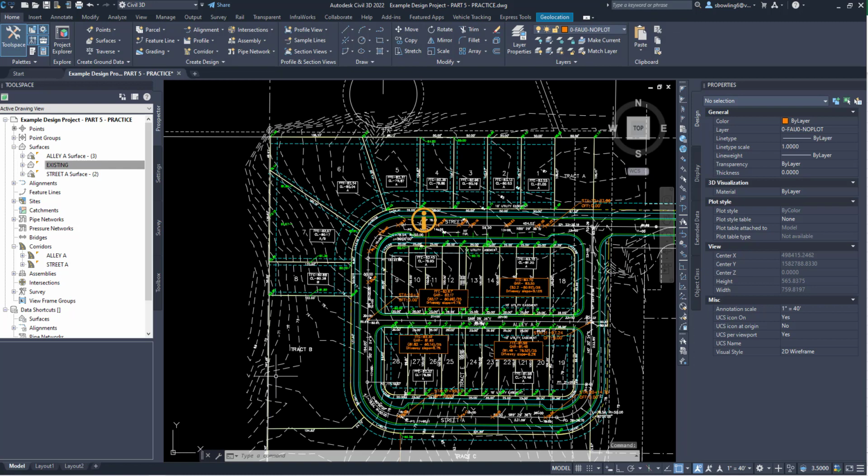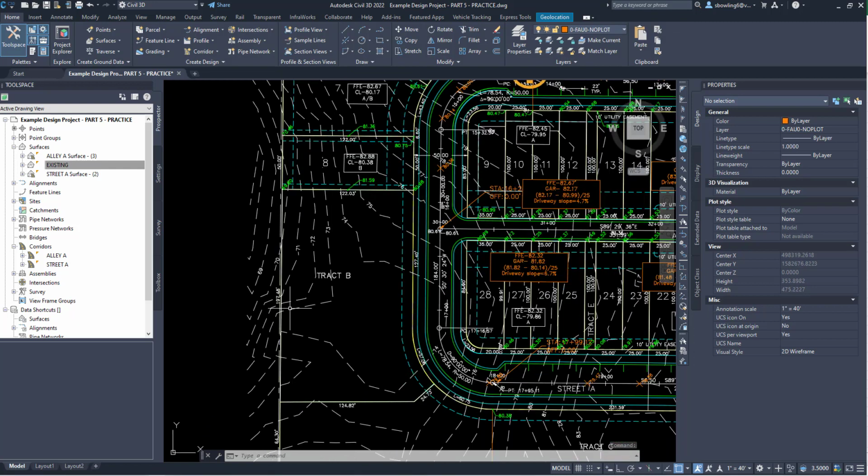I go okay. So the natural ground out here, the lowest elevation is basically, I'm going to say it's going to be a 71 for our site. Okay, we can tie easily into a 71. So that's what I'm going to make the bottom of pond, because I'm going to assume that 1 foot below the 71 elevation, so basically 70, is going to be our seasonal high water table. It could possibly be 69. I'll have to take a look.